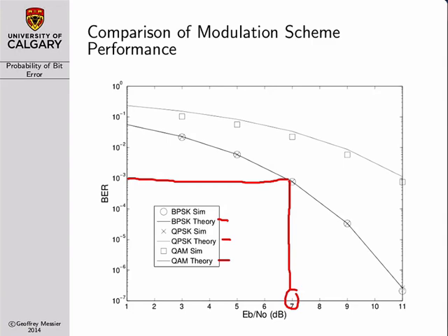And as a result, the bit error rate predicted by the equation is slightly higher than the simulation, but it's not too bad. We would consider this a fairly tight bound. If you consider the horizontal distance between the point and the curve, it looks like it's maybe 1/4 of a dB, which is not too bad.